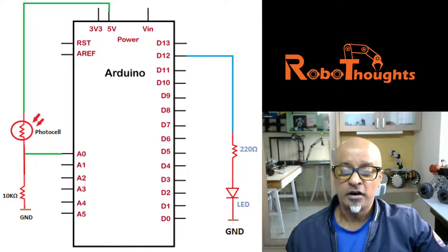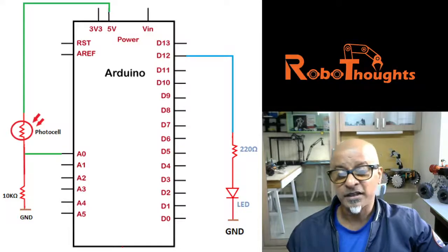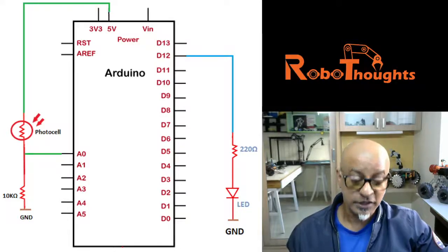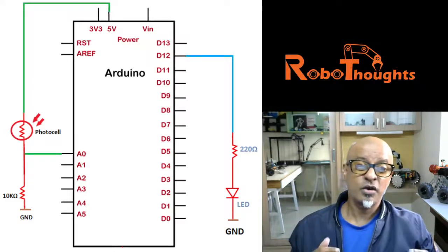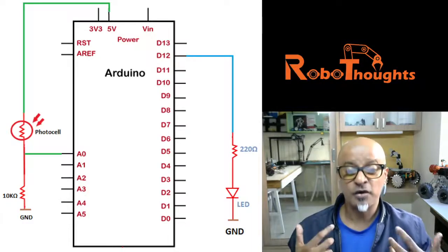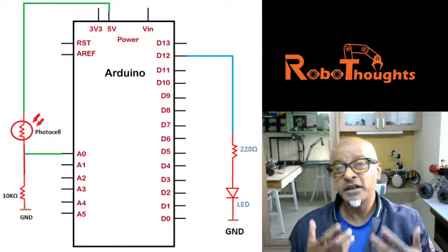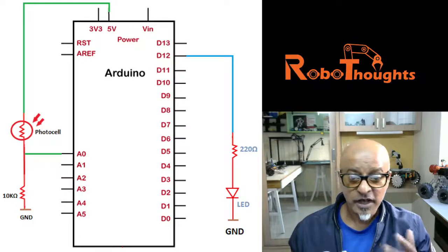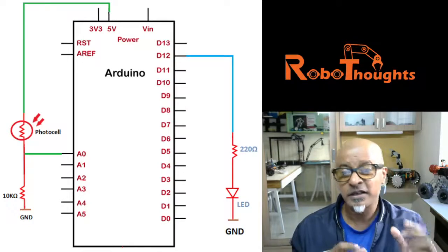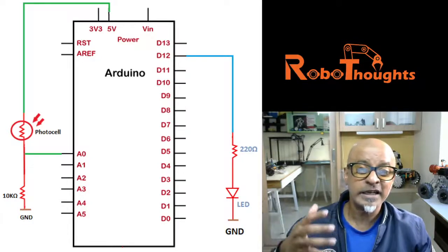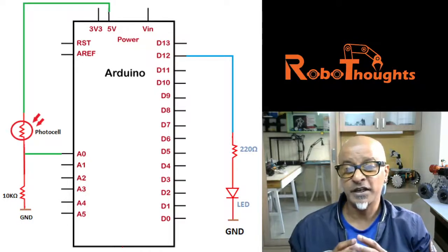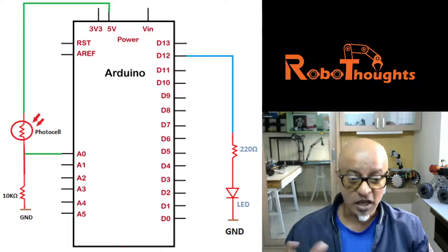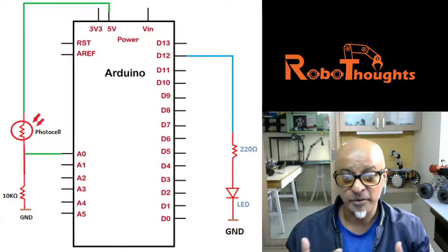It is defined as a light controlled resistor, also called an LDR or a photoresistor. It is basically a variable resistor that controls the resistance in accordance with the received light intensity. If the light is bright or dark, the resistance changes automatically.